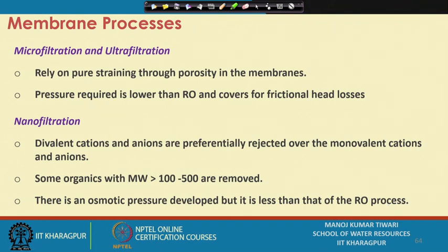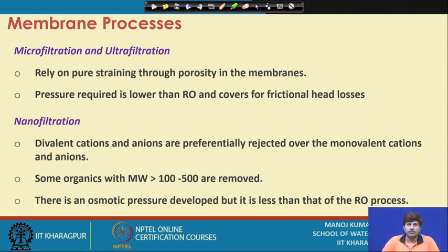So, if we see these different membrane processes, particularly the ones used in wastewater treatment, microfiltration and ultrafiltration are essentially just a size difference. They work on a similar principle, they are just pure straining processes through the porosity of the membrane.